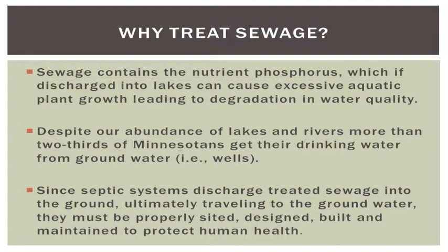So besides surface water, there's also groundwater that we do need to protect, and that's being protected from the nutrient nitrogen. Many private residences rely on private drinking water wells on their site, and therefore if the nitrogen from the sewage enters their drinking water supply, it could cause them health implications and health problems at that point. So the main goal of the ISTS rules and program is to match the problems in sewage with the treatment that is necessary to take care of those problems.